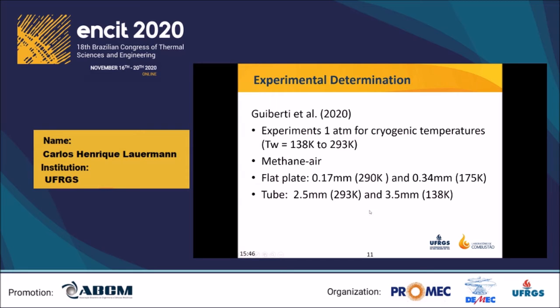And as we can see, for those lower temperatures, the difference of temperature between flame and surface is higher than for those cases at ambient temperature. So it is easier to stop the reaction rate, so the quenching distance can be higher.